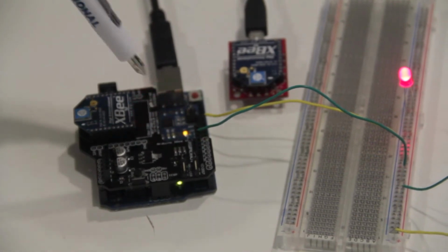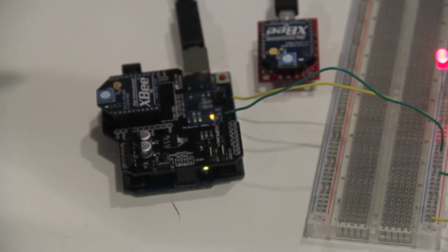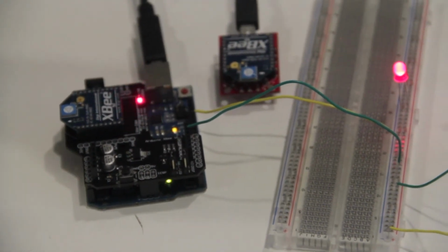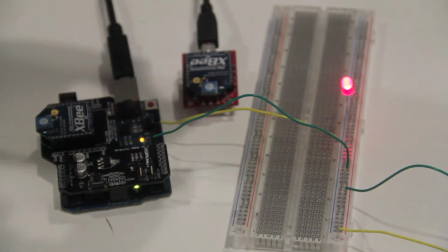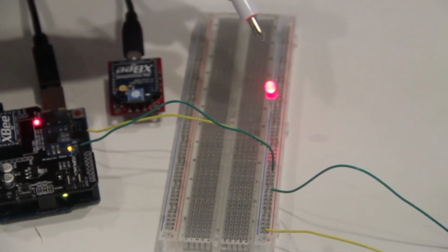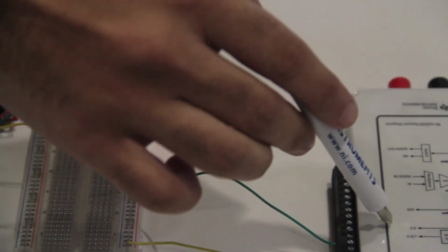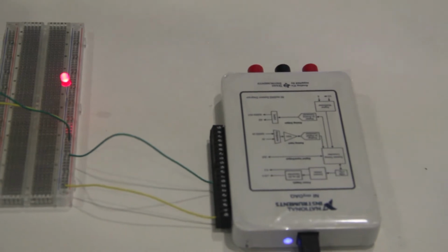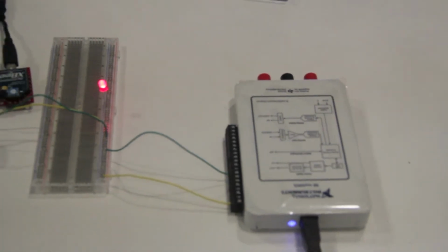All this computation is done by the Arduino Uno board, and the interrupt is generated to be passed on to the National Instruments myDAQ. Now this interrupt can be seen through the glowing of the LED, and finally the interrupt that is received by the NI myDAQ is interpreted by the LabVIEW software, which triggers the alarm.